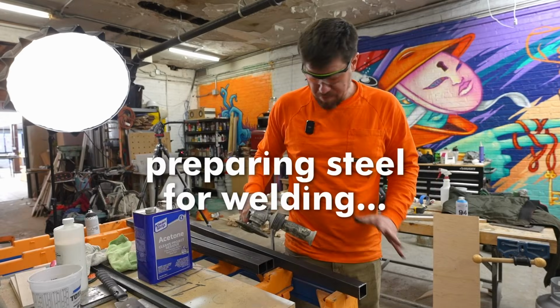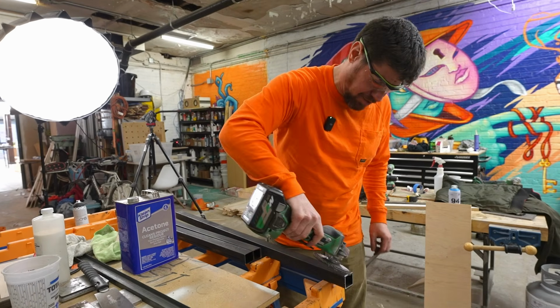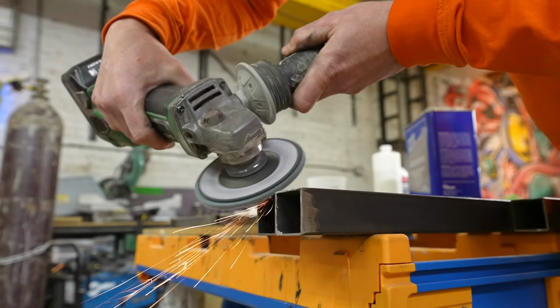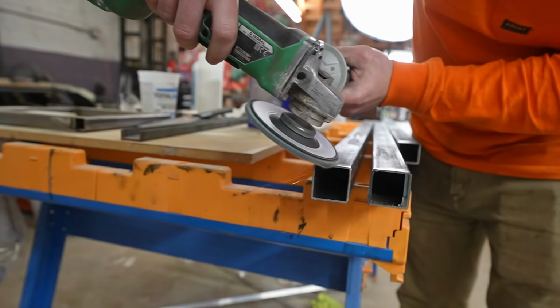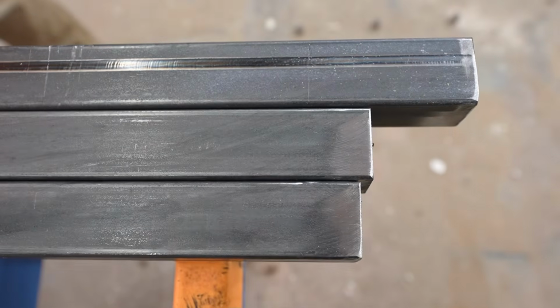So prep work's gonna be pretty simple. First thing we're gonna do is take a flap disc and basically grind off any of the excess steel that we got here from the cut, and make a little bevel so there'll be a little valley that we can puddle the welding material into when we do the weld. And then use a little acetone, clean up all the mill scale so that it'll take paint nicely.